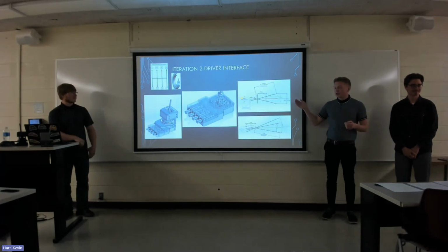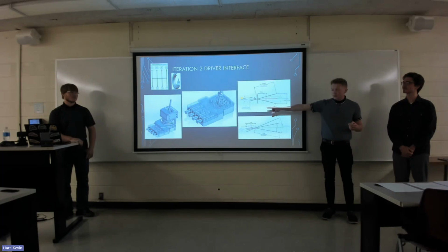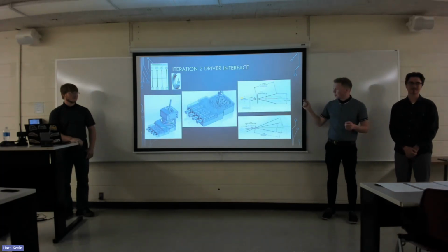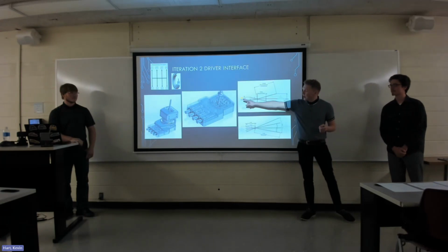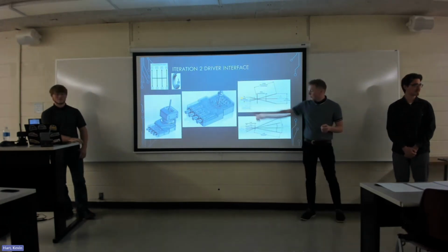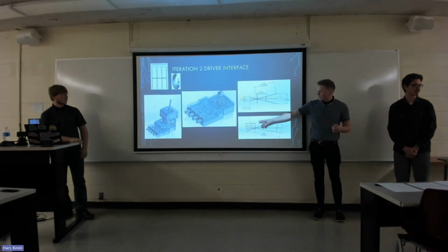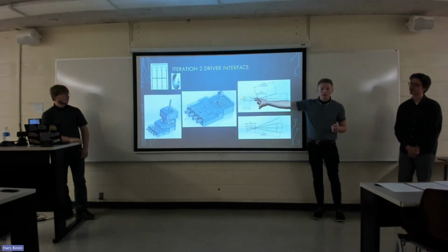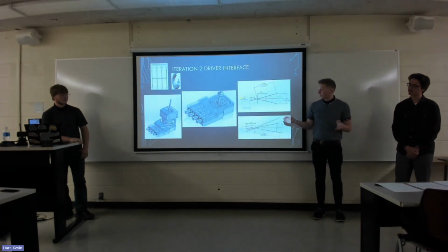Based on prior calculations, we needed a 35 millimeter output throw out of these rods out of the bottom of the shifter. To accomplish that, we had to lengthen this bottom of the shifter below the pivot ball 4.14 millimeters, which additionally spaced out our lateral travel, which made the slots a little wider, which wasn't a big deal.